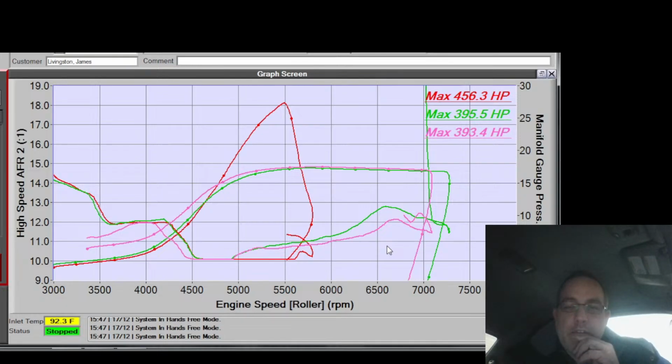I wonder if I have issues with the downpipe or the exhaust and where the wideband is. I wonder if that's even accurate. Honestly, that makes me doubt the accuracy of it. I mean, it did come down, but it makes me feel like there's an exhaust leak somewhere sucking in air. And I hit like a resonance and it's in there. Unless it's fuel system resonance, which does exist.